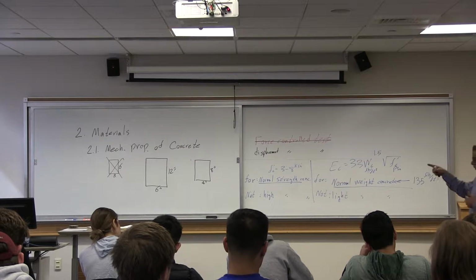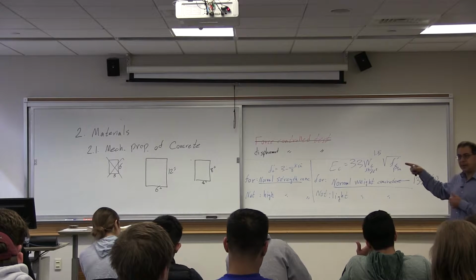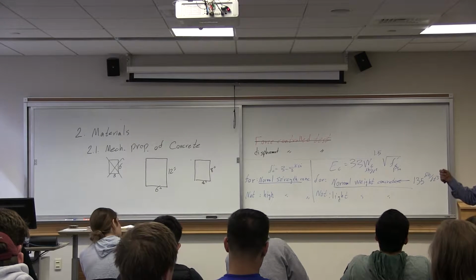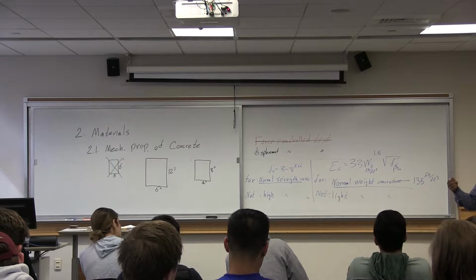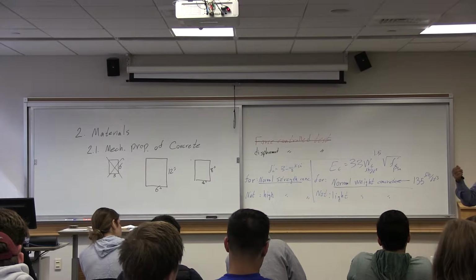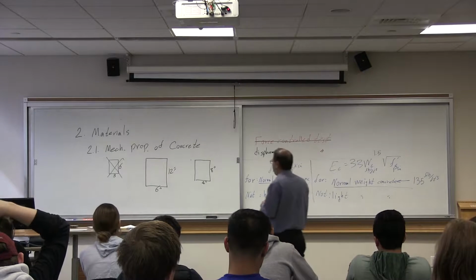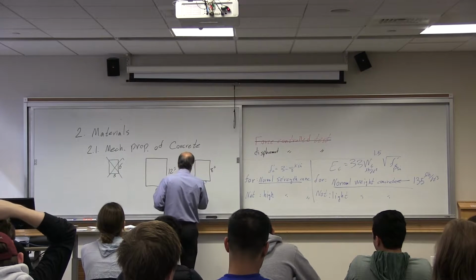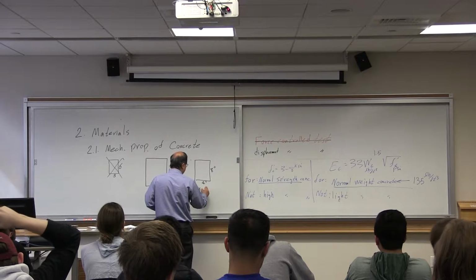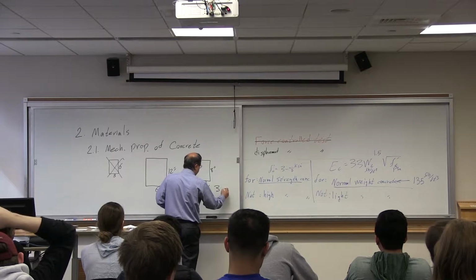If you are going to the smaller sample, it has been understood that the randomness of the characteristics becomes higher. That's why the code says if you use 4 by 8, you need to find the average of 3 samples.